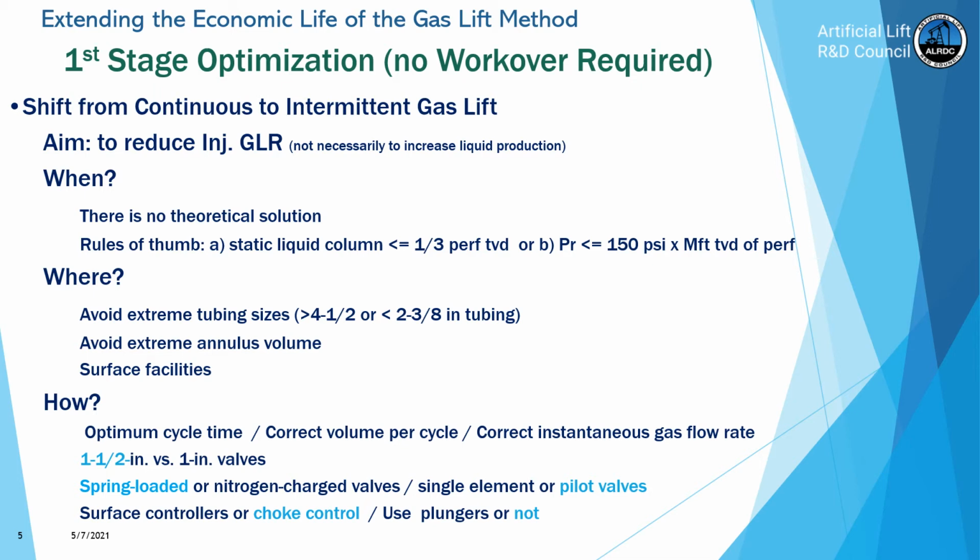So yes, you might end up using a plunger so that you keep the fallback losses at a minimum, in two cases: when the liquid velocity is not very high because the injection pressure is not that high, or when the point of injection depth is very big.